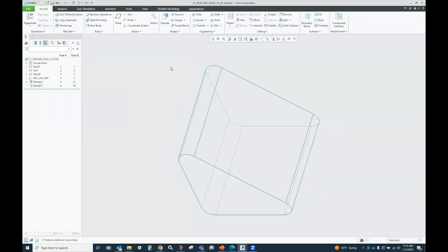So just, again, a reminder that Creo will never reuse an ID. If it has a new piece of geometry, it has to give it a new ID. Okay, unless we tell it otherwise, and I'm going to show you in a moment how to do that. But for now, just keep that in mind. We need these IDs for the features to regenerate. If an ID is missing, the feature is going to fail.